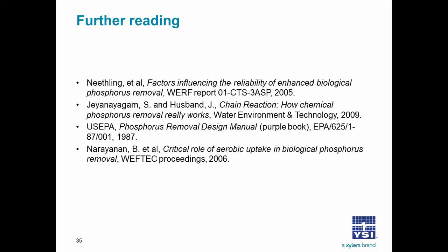One complication, though, is that sludge is, I don't want to say unstable, but if it's not handled correctly or stored properly, bio-release of that phosphate will occur, and when you decant or when you dewater, that phosphate will come back into the treatment plant. So that's really the complication with bio-P sludges.